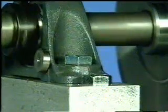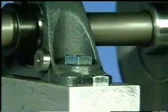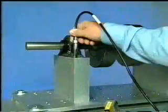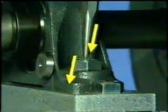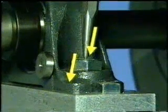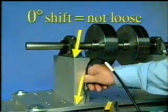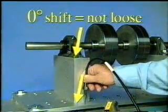When a component is loose at the mounting positions, the foot tends to hammer against the bolts and the base plate. Measure the phase on the bolt, the foot, the base plate, and even the floor to determine the movement. A loose mounting produces a 180-degree phase shift from the bolt to the foot, and from the foot to the base plate. If there is no phase shift between two of the components, such as the floor to the base plate, there is not a looseness problem there.